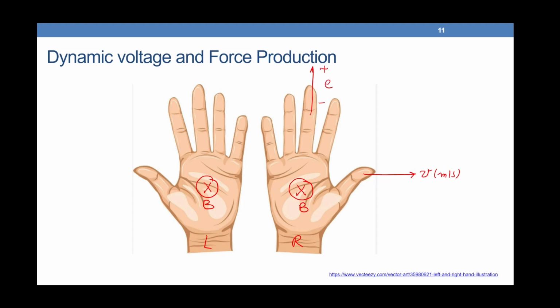On the other side, if we succeed to push a current I in the conductor, we get a force F in this direction in Newton. So please note that if we have the flux in the same direction, the fingers are pointing to electrical quantities while our thumbs are pointing to mechanical quantities.